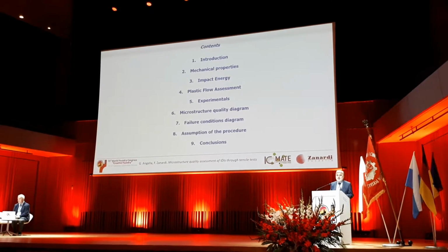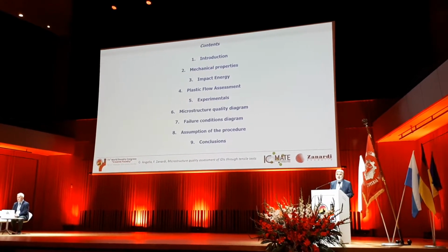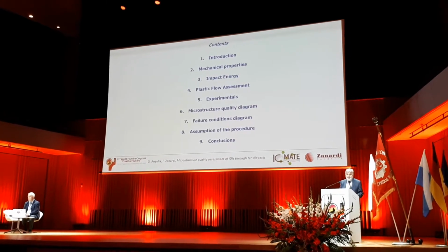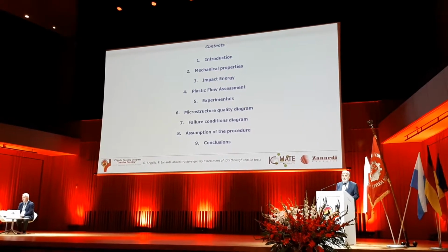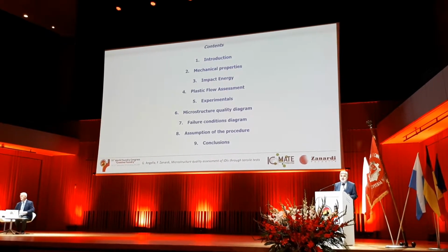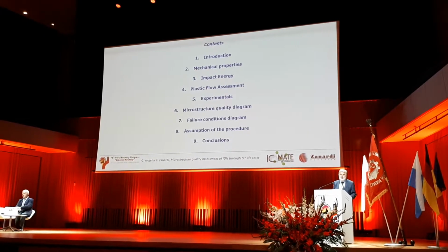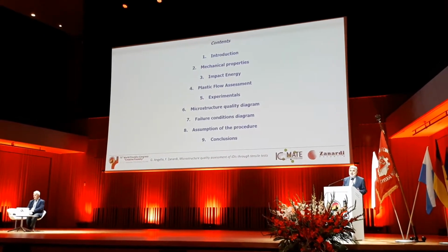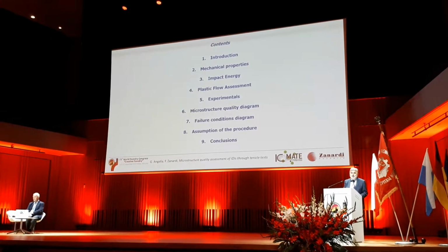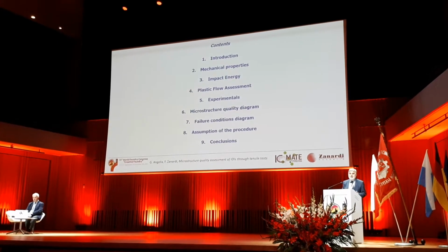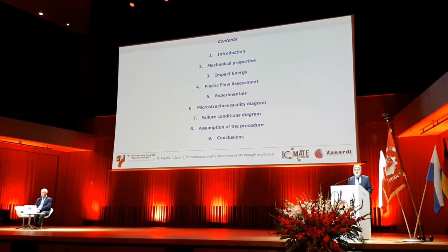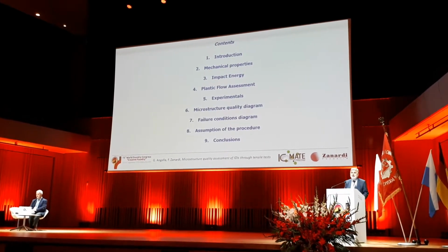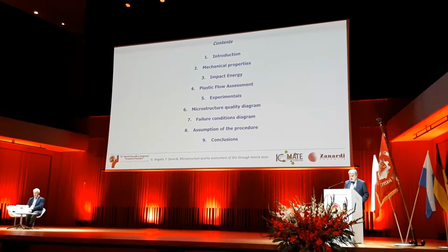The first one is the process control that we get with the tensile test, and the second is giving designers the confidence on our material, mainly ductile irons, compared with steel, and showing how we are able to use the plastic flow curve in designing when overloading and impacts are concerned. That is one main limitation for the wider development of ductile iron in comparison with steels.